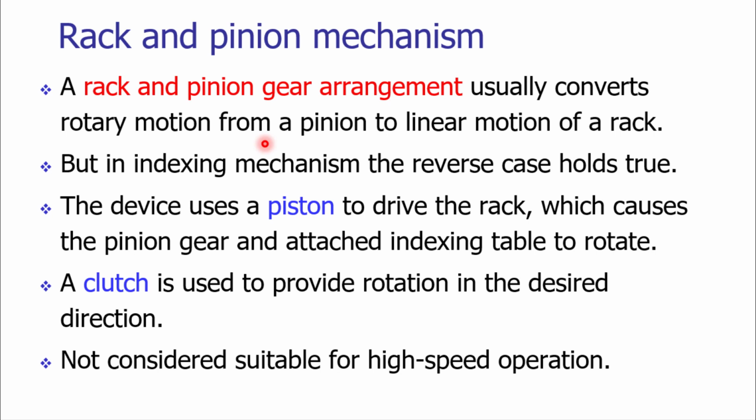The rack is again a mechanical element which is having teeth, and we can consider the rack as a small portion of an internal gear with infinite radius. We will see the diagram of the rack in the next slide. But in indexing application, we need the reverse case. So what is the reverse case? The reverse case is we need to get the rotary motion of the pinion due to the linear motion of the rack.